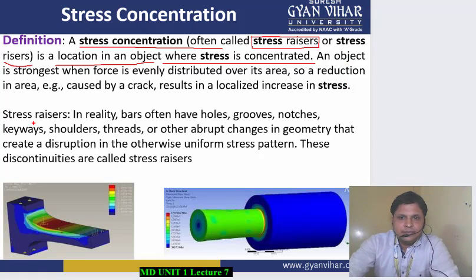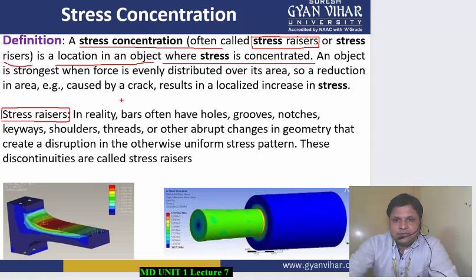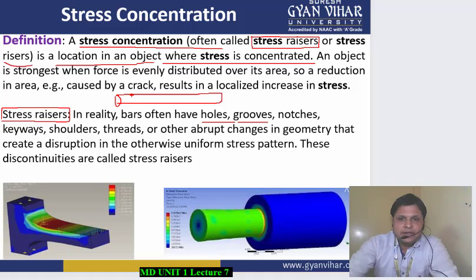Stress raisers in reality: bars often have holes. We are talking about the bars. If there is any rectangular bar or circular bar, it often has some holes. There might be some holes in it, there might be some grooves in it. In the case of a shaft, you have seen that there are keyways, so that you can insert the key. To insert the key, there are keyways in the shaft.